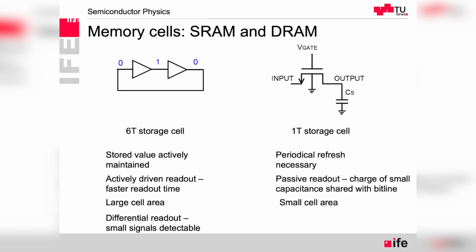But really the great benefit is that we can make those cells very small, and in fact the processes which are adjusted for this kind of DRAM cell have special capacitance options which are not available in standard CMOS, but will have a very compact capacitance. Very often they are 3D structures, so not just done with planar technologies. And then the single transistor and the capacitor can be integrated in a very dense, small area, and then we can have a much denser memory cell per unit area.